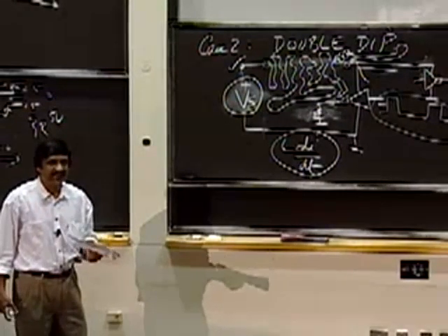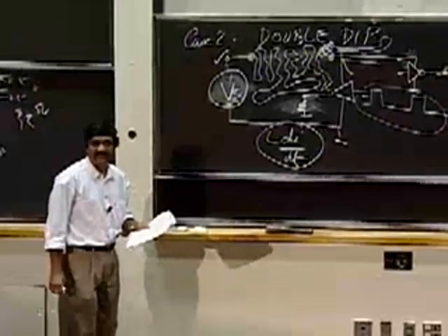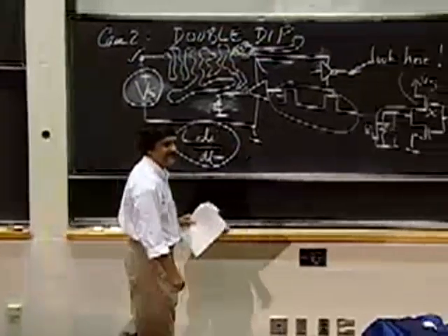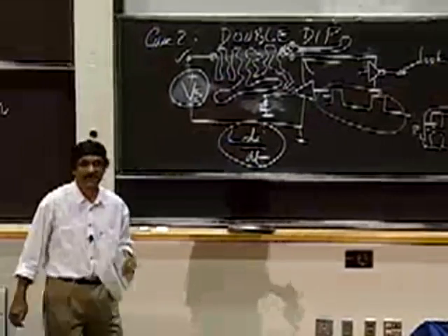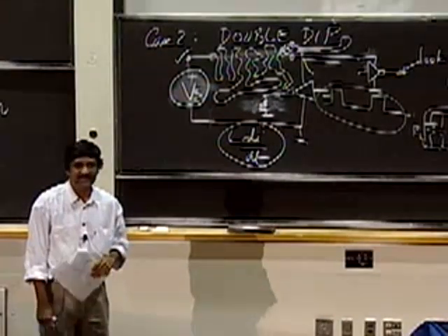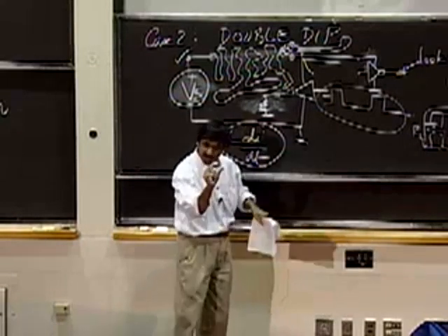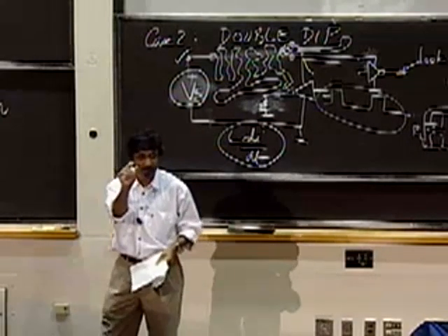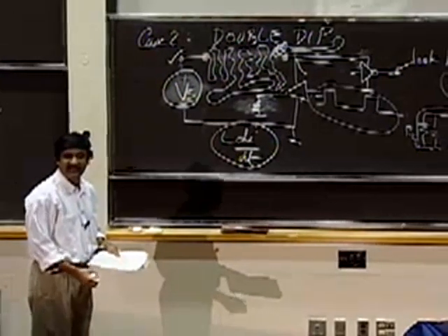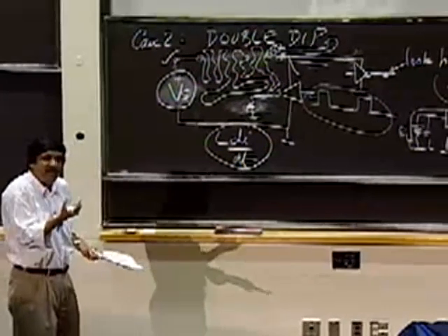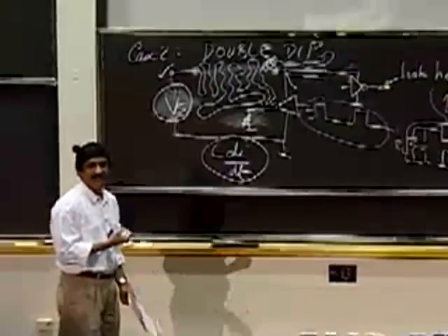But again, remember that what's small to you may not be small to the circuit. Let's say, for example, I'm Intel, and I'm building a 10 gigahertz Pentium 6 processor. 0.1 nanosecond is my cycle time. There, even a small itty bitty wire can be a real problem. Distributing power throughout a 1-inch chip that's clocking at 10 gigahertz is a really, really hard problem.